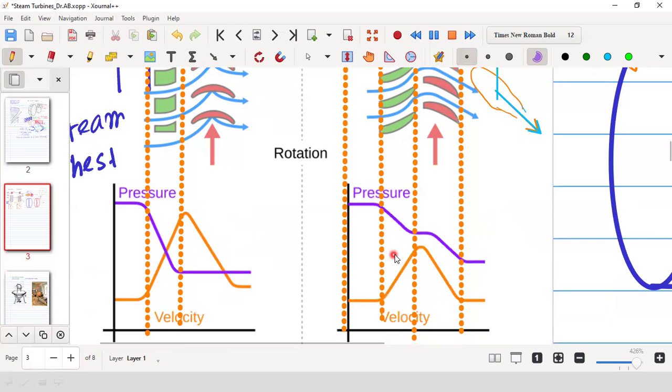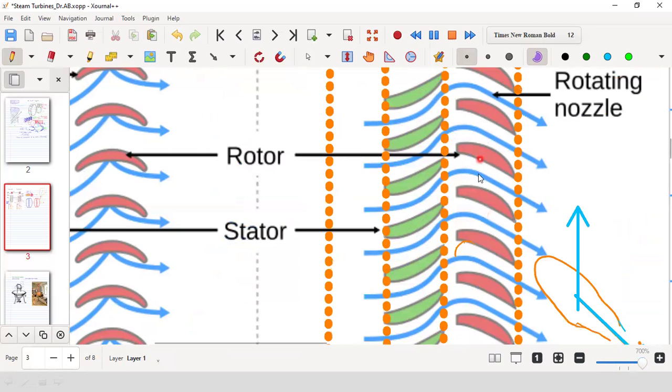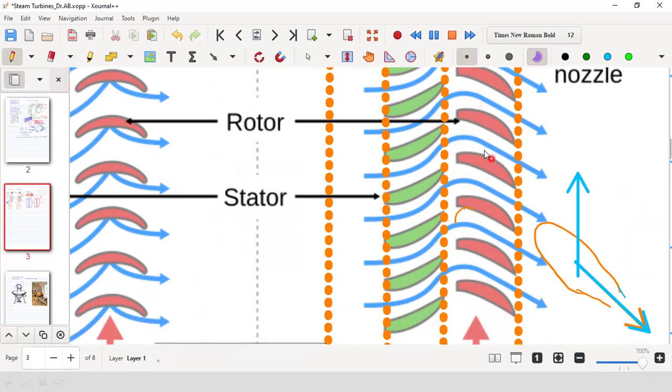Now what is reaction? Reaction means on the nozzle there is a change in velocity, and that is striking the blade. So due to that striking, the blade moves. Along with that, in the blade passage also, in this zone, there is further pressure drop. That means when the fluid moves through this, it suffers a pressure drop, and therefore, as if like a balloon, you can consider as if there is a balloon, and due to the movement of the gas, the pressure reduces, and therefore there will be a reaction.